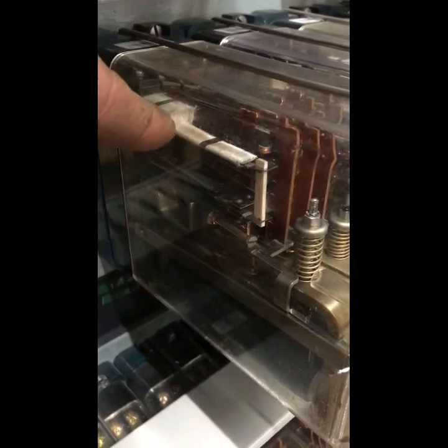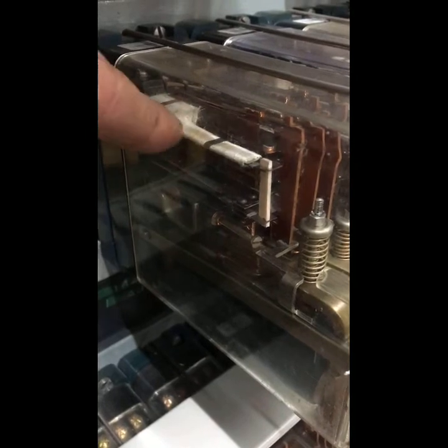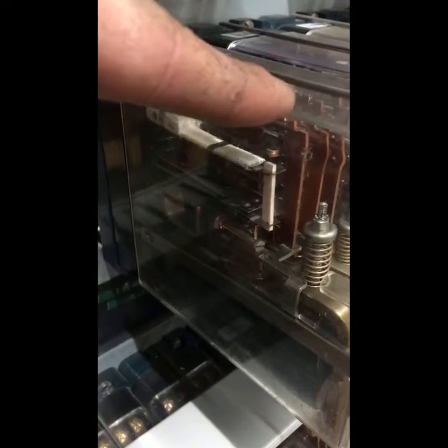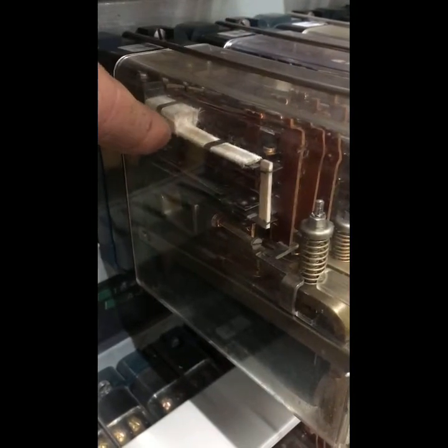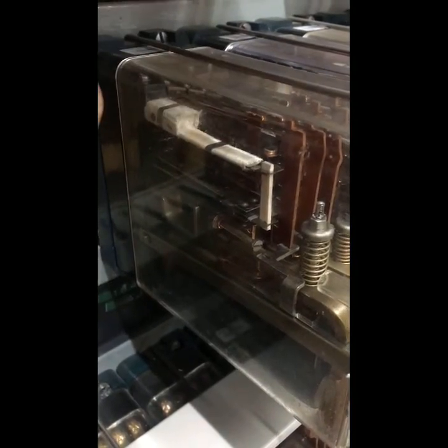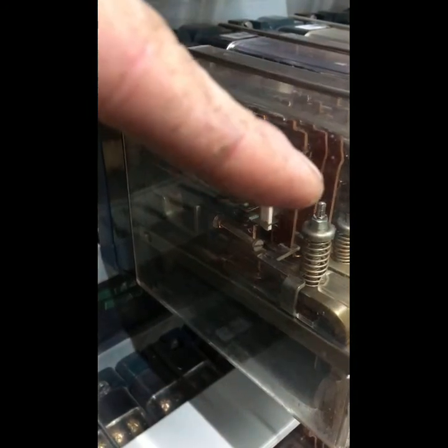A timer relay, to function correctly, has to time itself. So when you energise this, yes, it will bend, that will break the contacts. That will make a set of other contacts which will then give you your time. It'll take a certain length of time for this to operate, to bend, to go across. If it was a motor timer, it would take a certain length of time for the motor to transfer around and make the other contacts.